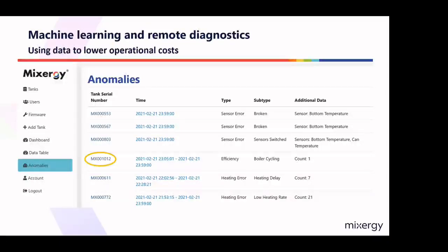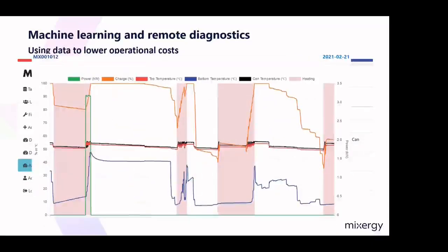So pick on tank 102, this is live data from earlier this year. When hot water is generated, we should have a nice, steady, sharp rise. If we see what we call the jaggies, where the cylinder coil is going hot, cooler, hot, cooler, hot, cooler, this is telling us that the gas boiler is turning on and off and cycling. So a couple of things machine learning can do to save energy.